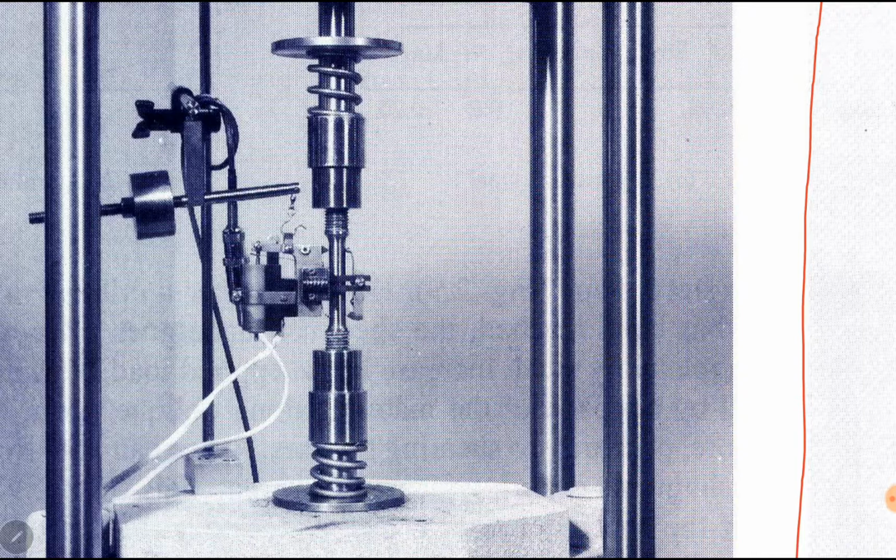Length is already given. We know all of the values. We can find delta B using this expression. P is actually force AB, 60 kilonewton. Okay, this is compression, so it is minus 60 into 10 power 3 newtons. Length is given, area is given, and E is given. E is in gigapascals. We have to convert it to pascals.